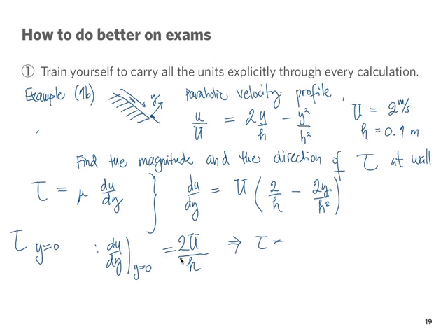And so now we can calculate tau is equal to mu times du dy. And I have all the data. I'm skipping some things. It was a layer of water, so we go to a table and we get the mu value of water, and it is equal to 1.12 times 10 to the minus 3 Newton second divided by square meter.